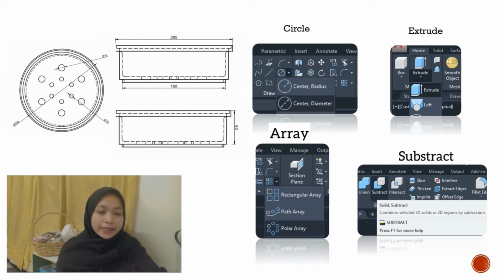Next, after we extrude the object, we use the command subtract on the circle of 190mm with the circle of 180mm. Then I make a new circle of 190mm and 200mm at the top of the object, and as usual we use the command extrude to extrude the circle at 5mm height, and then subtract these two circles, 200mm and 190mm.